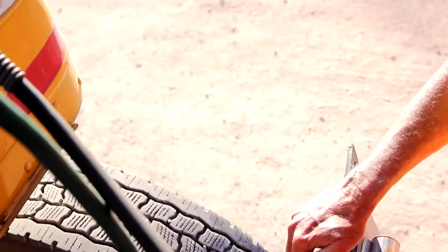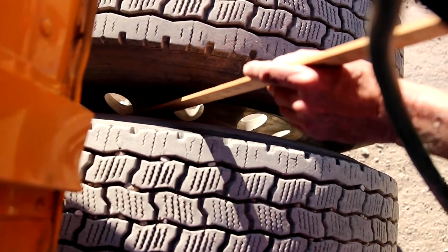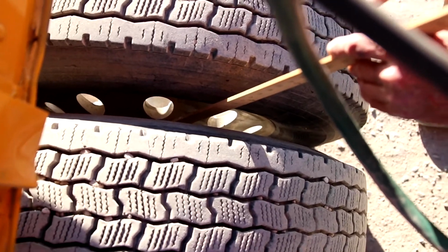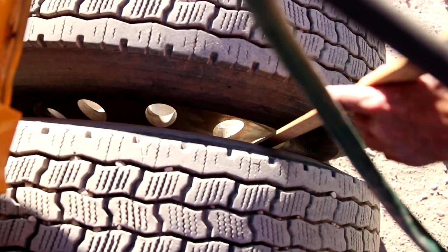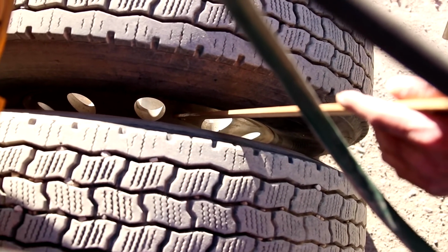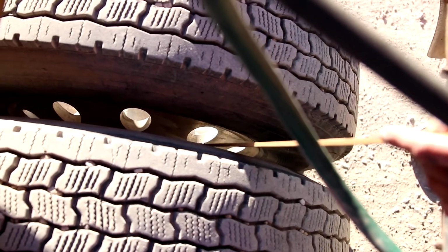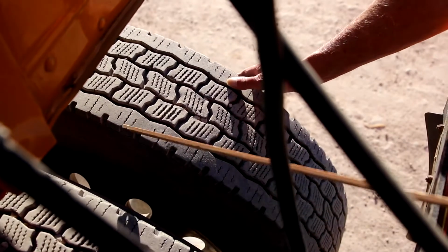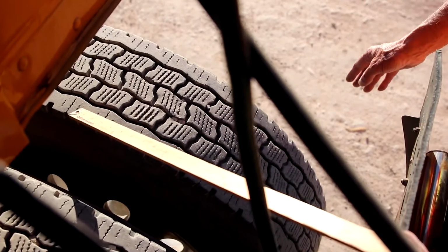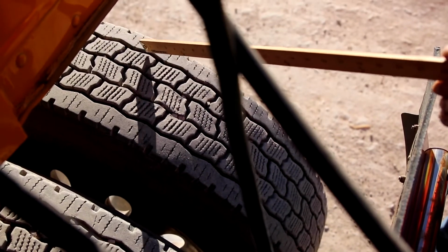Then coming to where the rims meet or butt together, there is no space between my rims, no daylight basically, no trash or debris inside the rims. This rim, the outer rim, inside of the outer rim, again, not damaged or broken, no illegal welds. My inner and outer tire wall is free of abrasion, bulges, and cuts for any type of blowouts. And again, the tread is wearing evenly and 2/32 of an inch in each major groove.